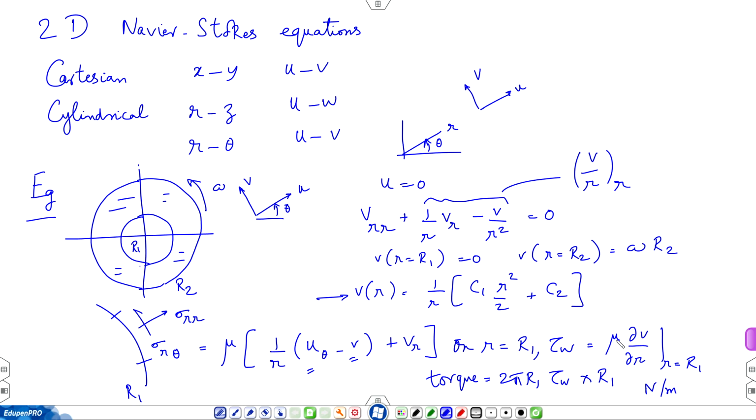Would you say you would prefer to use it in liquids or in gases? Can you use it in gases? Yes, except that viscosity of gas is very small, and the twist it is going to produce may not be measurable. But if you use it in liquids, particularly oils, the twist will be very large, because viscosity is very large.